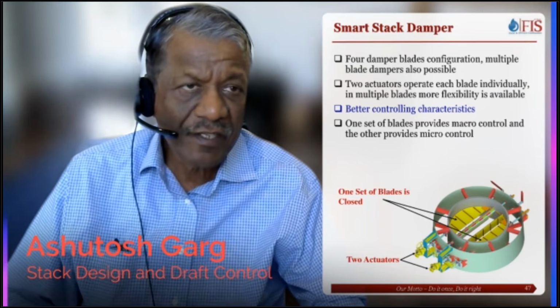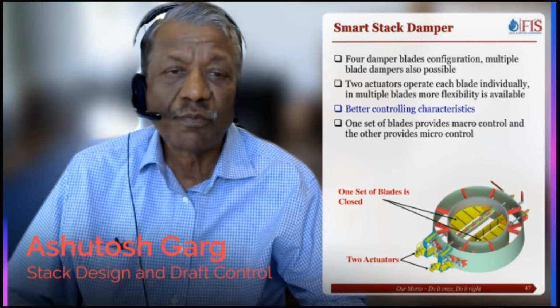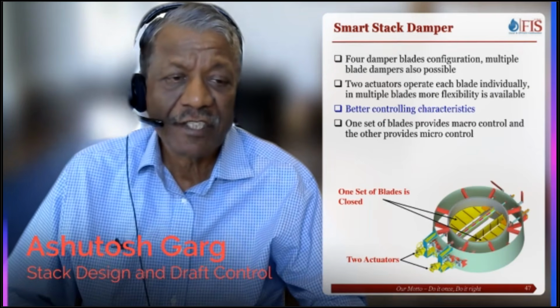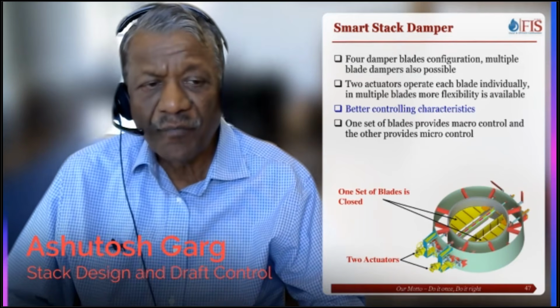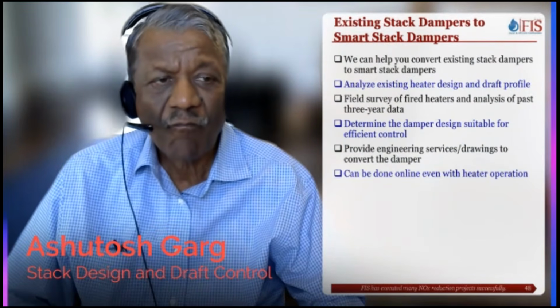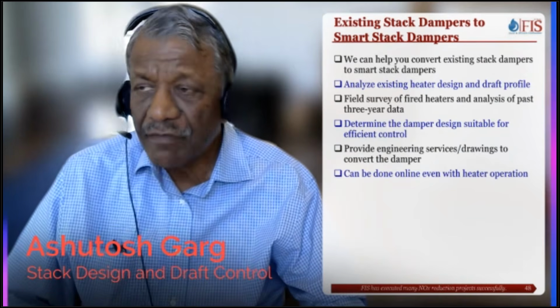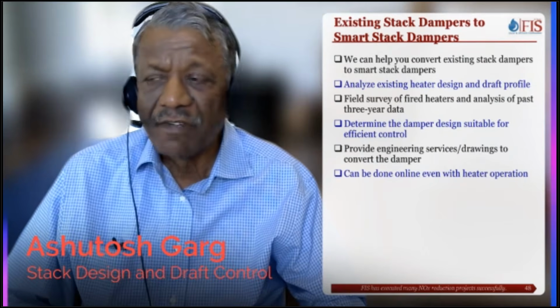These heaters were suffering from high excess O2 issues like 8% O2, 10% O2, and we are trying to control that. We have also supplied a similar damper to a company in Israel. And if you have a stack damper, we can convert it into a smart stack damper at a very, very low cost.